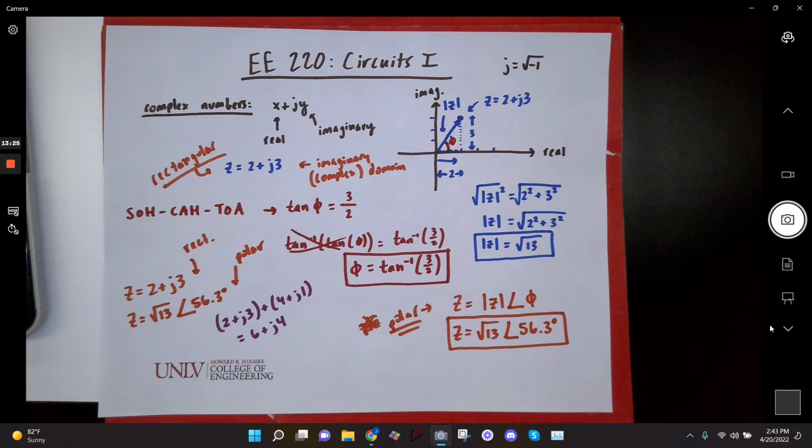Yeah? So what does multiplying and dividing these phasors tell us about the signals? Why are we doing it? Let's say we have a voltage phasor and a current phasor, and we want to do Ohm's law. We can find the impedance phasor, because V is equal to IR, right? Or we have the impedance phasor and the current, and we want to multiply the current times the impedance to get the voltage in the circuit.